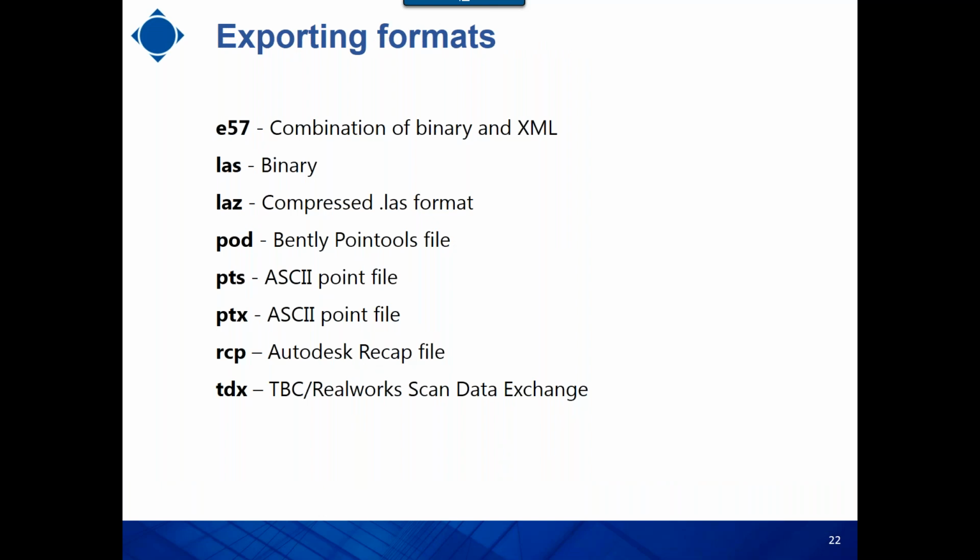Some of them are industry standard, some of them are for a specific brand. Let's say Recap, which is very popular, is for Autodesk Recap. We have the ASCII format, PTS, PTX, Bentley Pointools POD, LAZ, LAS, E57, and TDX is the data exchange format between TBC and RealWorks. These are the available formats that you can export your point cloud, or at the end of the day, if you don't want to export the point cloud that I showed you, you can use the available commands inside TBC to create survey points and send them to your stakeholders.